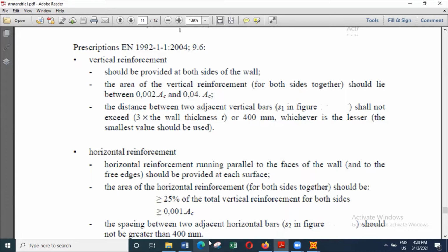And if you think the stresses are high, there's a possibility of continuing part of the column reinforcement and anchoring it within the wall, so that any stress concentration effect can also be well taken into account by the column reinforcement. So that's the way that we can make use of strut and tie models for the design of walls supported directly by the piles.